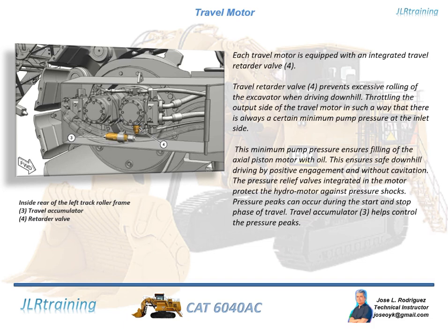The pressure relief valves integrated in the motor protect the hydromotor against pressure shocks. Pressure peaks can occur during the start and stop phase of travel. The travel accumulator, 3, helps control the pressure peaks.